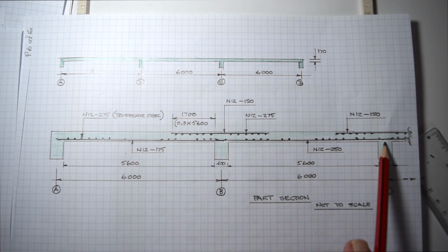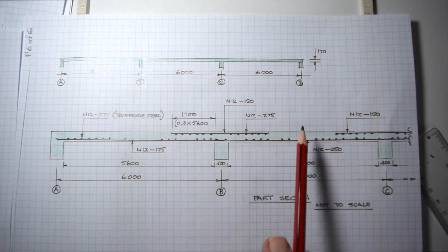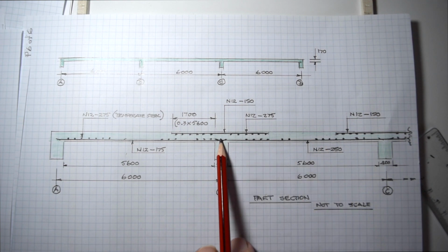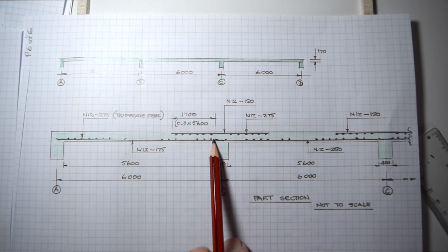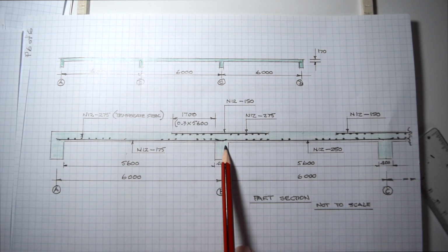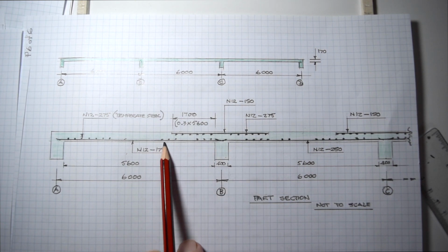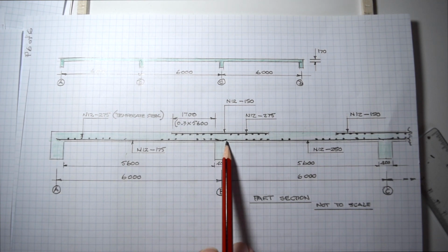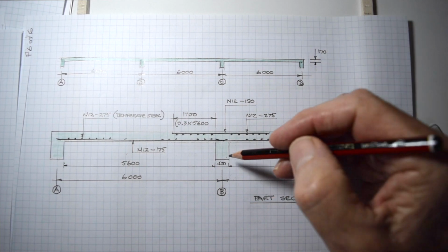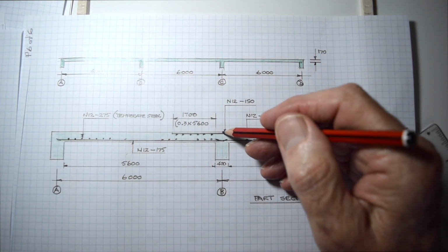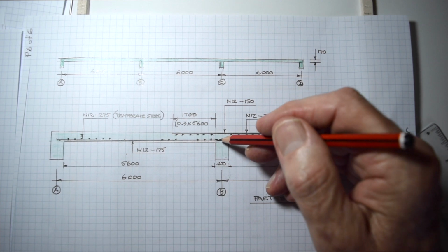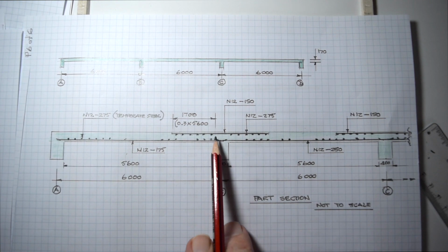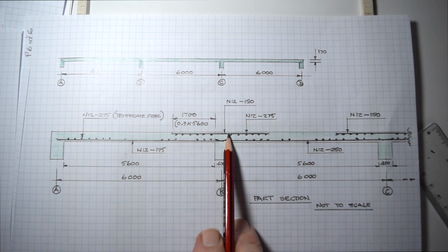N12s at 250 there because your moment was much smaller. Do you remember in this center span, your moment was a lot smaller, so you end up with N12s at 250s. This is where the bars just run over past each other. They're lapped against each other over the beam. These dots that you see there are the temperature steel, the transverse steel. It doesn't run through the beam because remember that you've got beam steel in there, a ligature, and you've got your main beam steel. So it's pointless running these bars through the inside of that. They don't serve any purpose. Or at the top, because you've got tie bars for your beam over there.